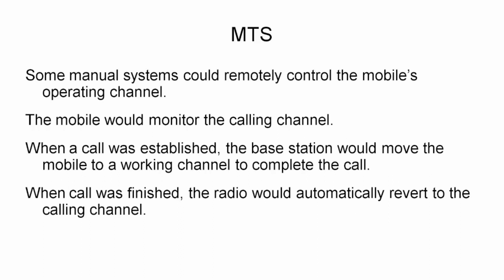It was sort of a semi-automatic system in that the channel selection was automatic, but the dialing was still manual. The mobile would monitor the calling channel. When a call was established, the base station would then move the mobile to a working channel to complete the call. When the call was finished, the radio would automatically revert to the calling channel.